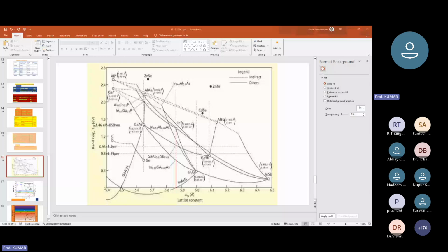Now I want to tell you one important thing. Many times we are told about semiconductors by drawing two lines: one line is given as a bottom line, which is called the valence band, and a top line, which is called the conduction band. There is a gap between these two, which is called the band gap, and you are told that this is a semiconductor. Actually, the line is only a representation, a straight line. It should be drawn as a wave. So please understand, these two lines, the valence band line and the conduction band line, are not actually lines, but a representation of this wave pattern.